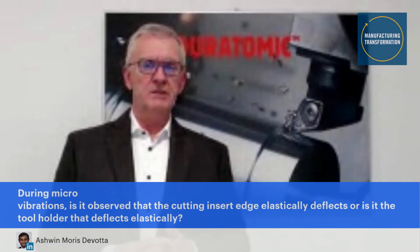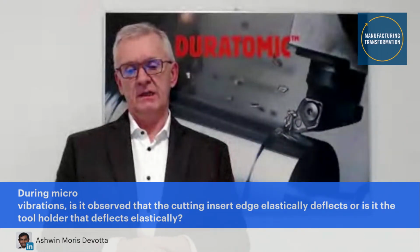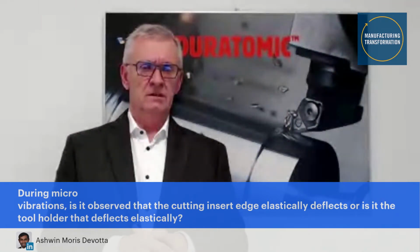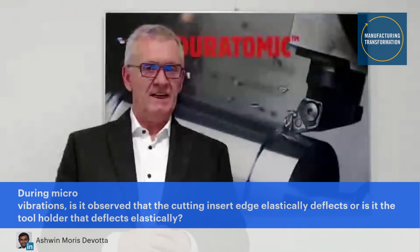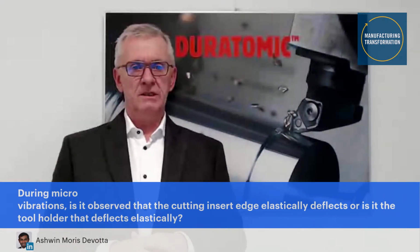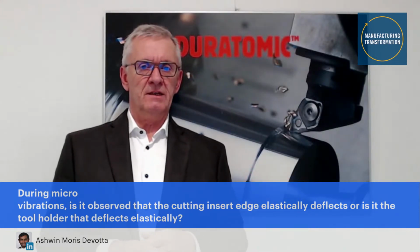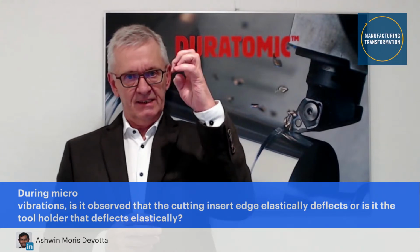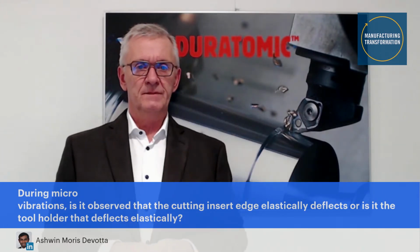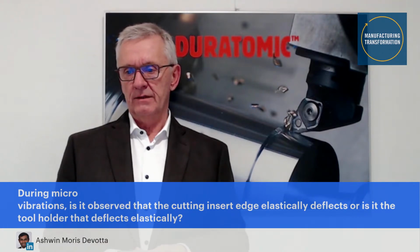For me, it's difficult to answer this question. Let me say, if you select a cutting material with a rather high hardness, it will be more the holder that deflects than the actual cutting edge line. The more you go towards softer cutting materials, the more it will also be the cutting edge line that starts to move. It's depending on the tooling you use.